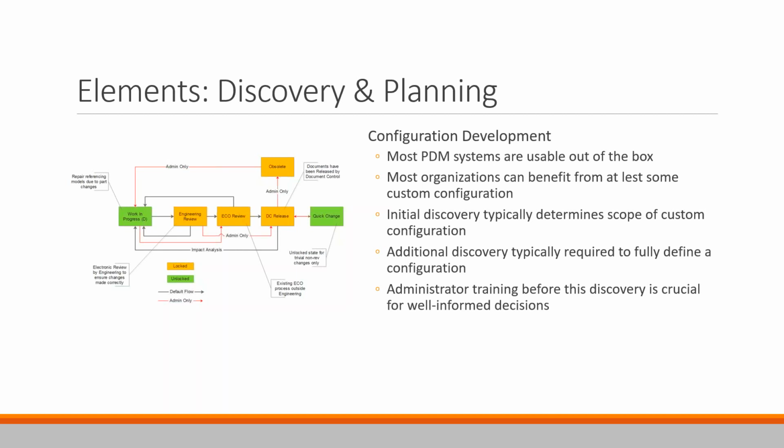two primary administrative duties with Vault. You might consider 3 of them. Autodesk Vault 2018, Professional and Workgroup, introduced a couple of additional administrator roles. It's a very nice new feature where the admin roles are separated. The classical view is there are 2 types of administrators for Vault. There's someone that administers the back end, like the server. They're responsible for making sure that if something goes wrong with the server, like if the web services need restarted or if there's a support issue and logs need to be provided, they need to know where those things are.